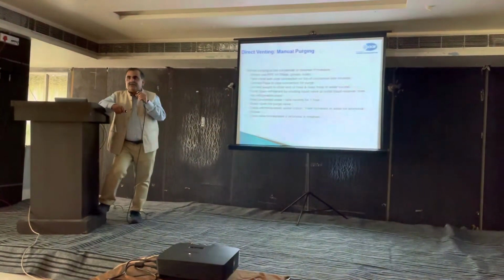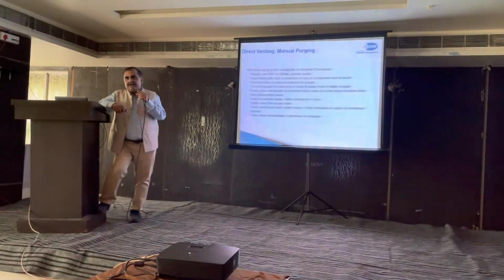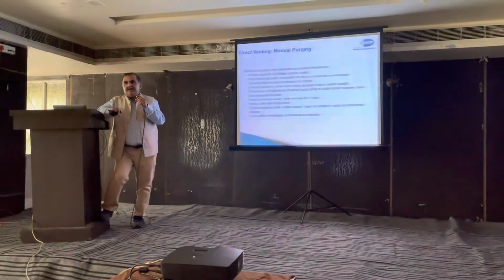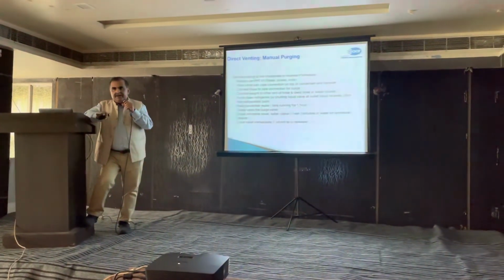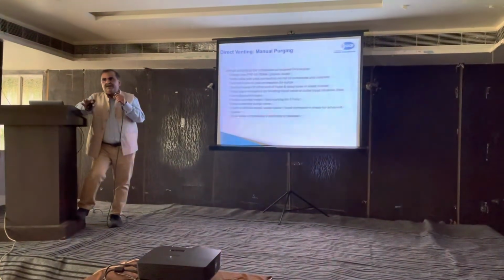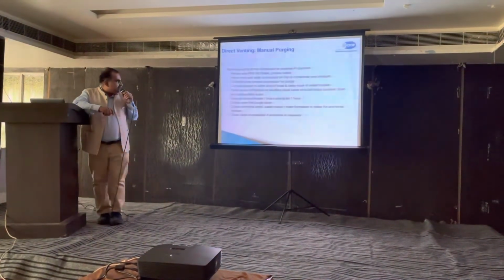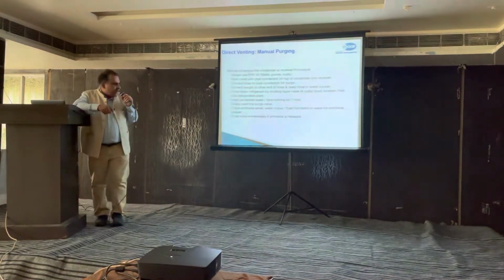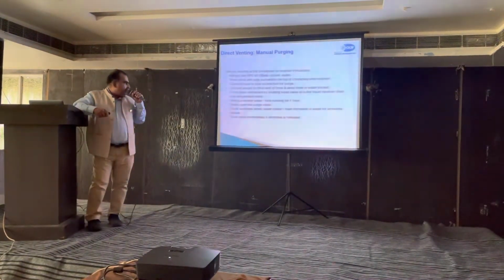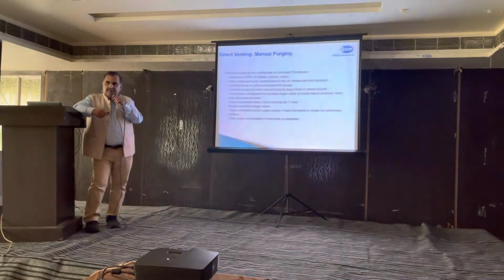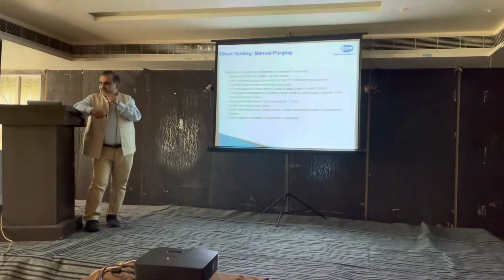So you have to make sure that your condenser is stopped and water is sprinkled on the condenser for sufficient time so that all the ammonia inside the condenser is fully liquefied, and then you can remove the air. This is the complete procedure given here, and it has to be very thoroughly followed by all the people involved. Otherwise it will affect the human being operating it. Leakage of ammonia is possible.